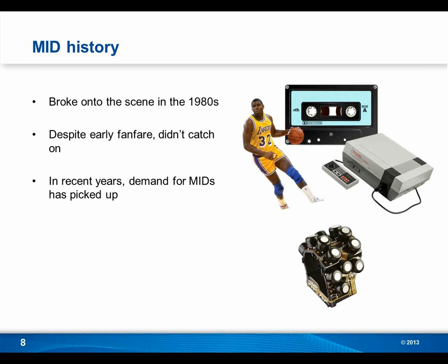Now in recent years, the last decade or so, demand for MIDs has really skyrocketed. And why is this? Well, today's world, it's all about miniaturization and increased functionality. So, as we mentioned, MIDs save space and they lower part weight by reducing components and bringing what would normally be a mess of wiring all into one single part. And that's a very appealing factor for those trends of miniaturization and increased functionality.